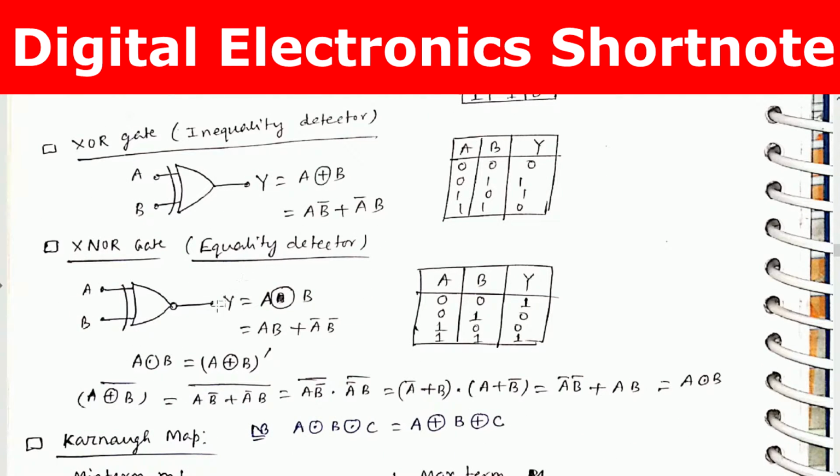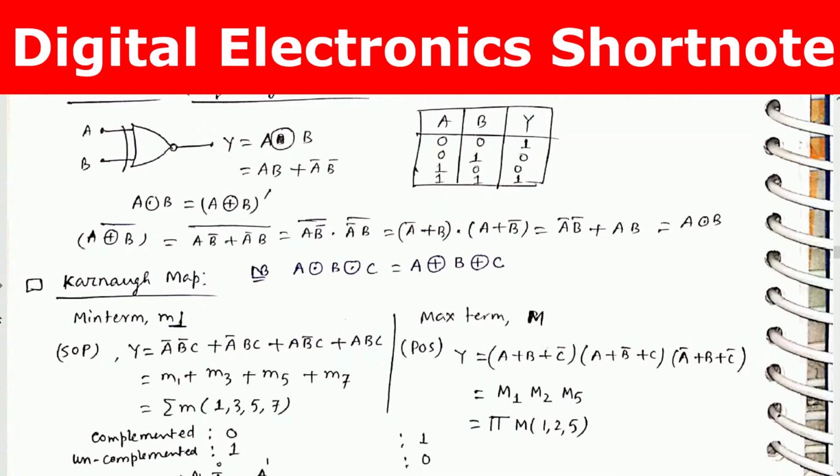XNOR gate, this is basically a combination of XOR gate and NOT gate, and it is called equality detector, and the output is given by Y equals A XNOR B, AB plus A complement B complement, which equals (A complement B complement) whole complement. Equality detector means when the inputs are equal, then only you will get high output. 0 0 equal, 1 1 equal, so you are getting high. 0 1 unequal, 1 0 unequal, so you are getting low output.